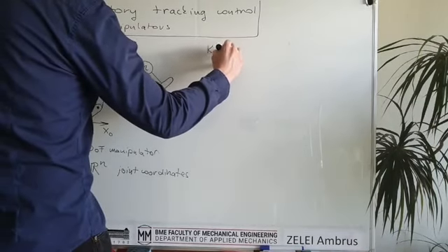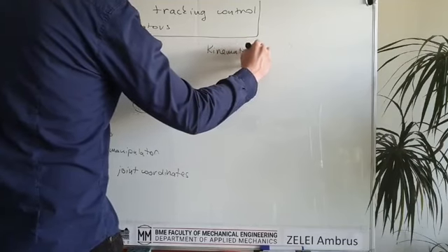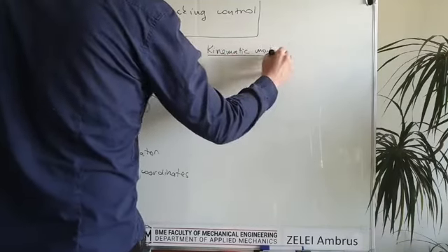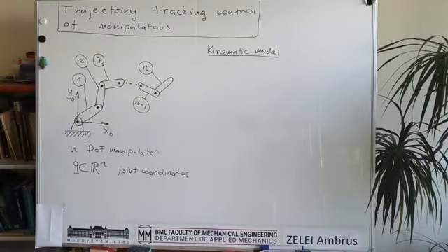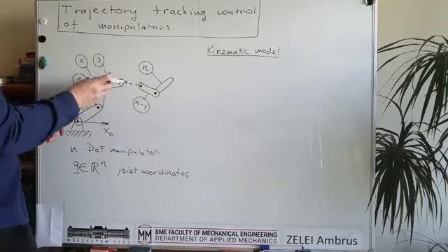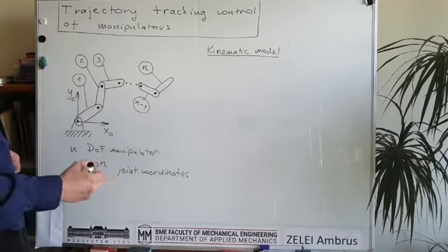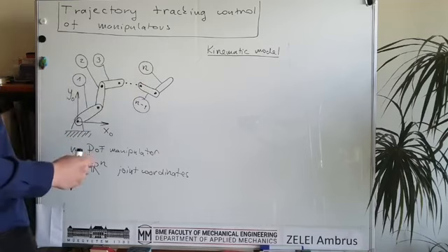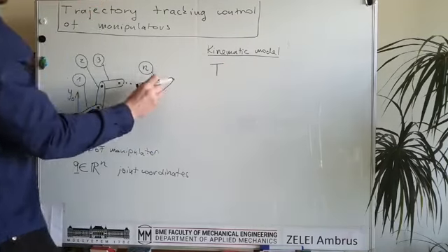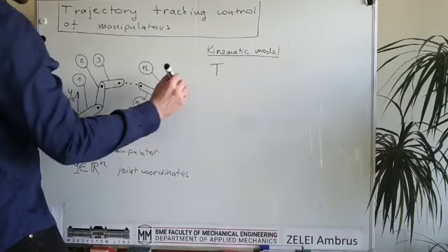It was the first iteration step in the Newton-Euler recursion to create the kinematic model, and the kinematic model is basically the ability to calculate the pose, which is the position and orientation of each link, or we can calculate the position of any point of the robot in the global system.